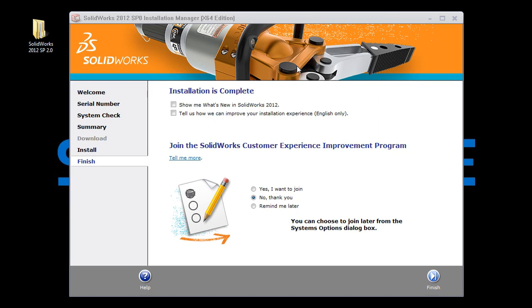If the installation fails multiple times, then the issues are generally more complex. Sometimes you have to reinstall a component that SolidWorks needs within Windows to be able to install, and sometimes you have to uninstall various programs or move a few things around in order to get it to work. If you are experiencing additional problems with your installation, and you're on subscription, you can contact your reseller and they'll generally help you out with fixing your installation problems.